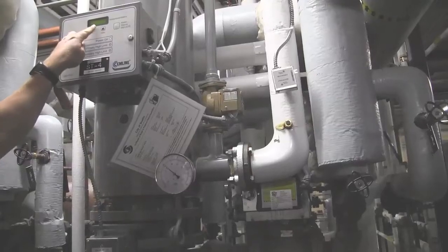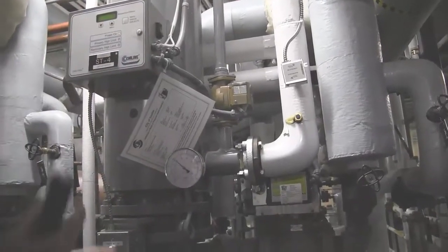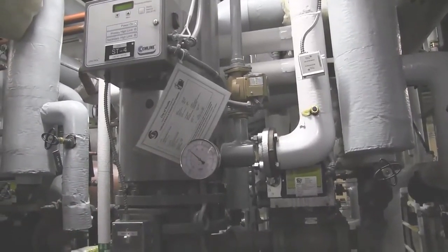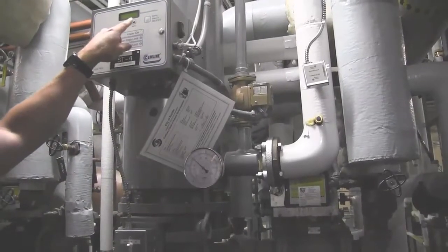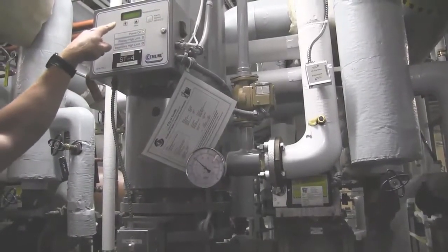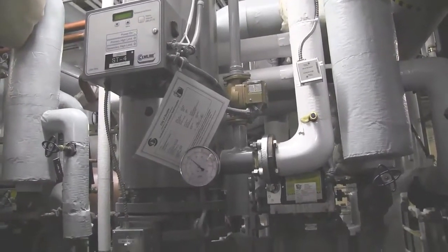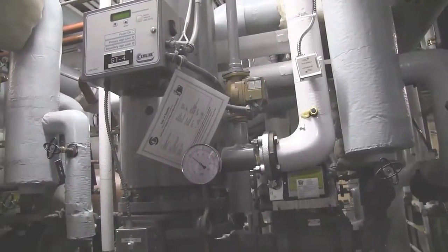That's giving you your temperature readings for both your primary and secondary sensor. If those have a differential of, I would say, more than 5, you have either a bad sensor or your circ pump is not working. They should be within 1 or 2, and as you can see right here, they're right on each other. That's the quickest way of doing it, and then if you did have an issue, we would tell you to get an ohm reader, read your sensors, and everything else. You go from there.